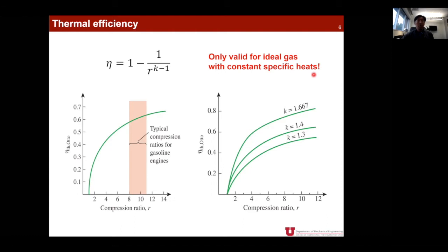If we use this equation, then you can get exactly the same value for the thermal efficiency as the value we calculated by using the net amount of work and heat input. But if your working fluid cannot be assumed to have constant specific heat anymore, in other words, if you use the fact that your specific heat actually should vary, and yes, it varies, then you cannot use this equation.